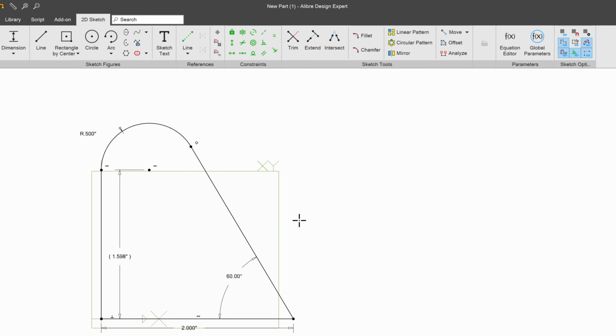And finally, I think I've got one last constraint. If I make 2 lines that cross each other, let's say that I would like to have a circle right at that cross. Well, one option is to use the intersection constraint. And what I'll do is I'll click one line, click another line to establish my intersection, and click the point on my circle so that it will lie right on that intersection. And as I update my sketch, the circle stays there.